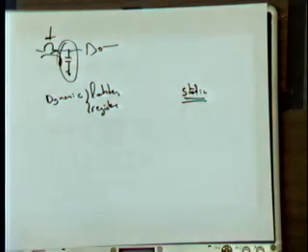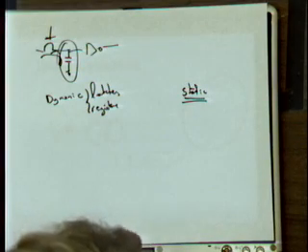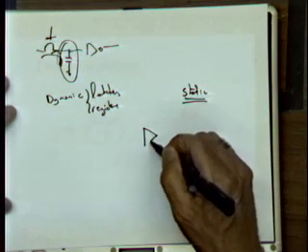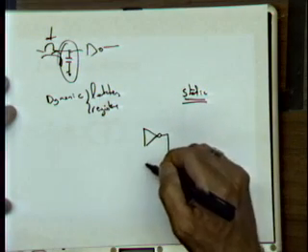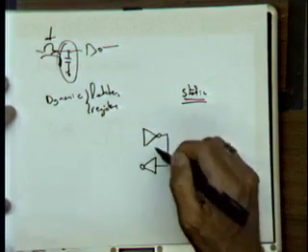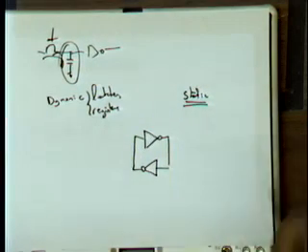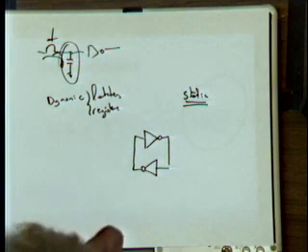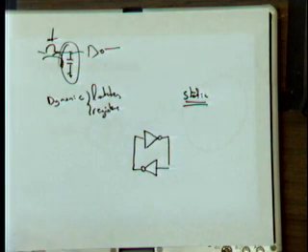The static version of a register is based on a very simple concept. The basic core of any static latch or register is this: that's my storage element. If I take two inverters and connect them back to back, I create something that remembers a value.